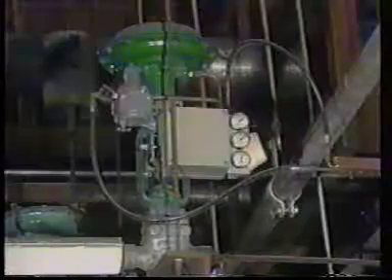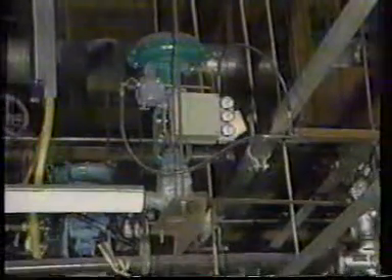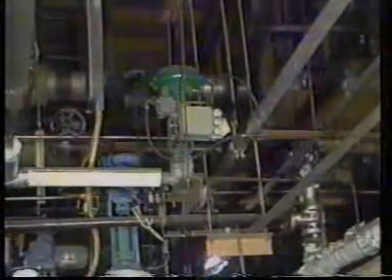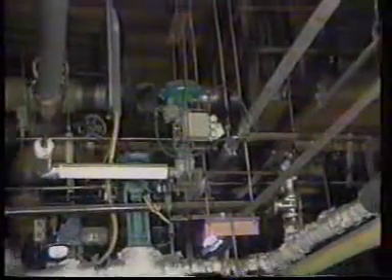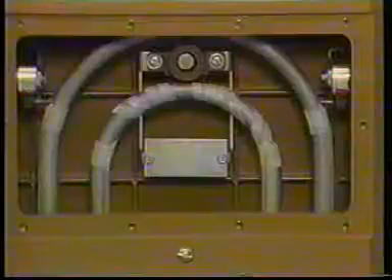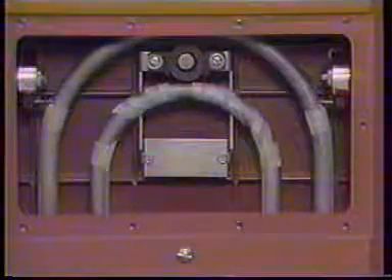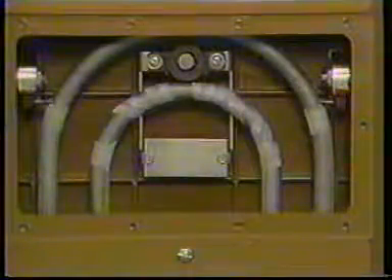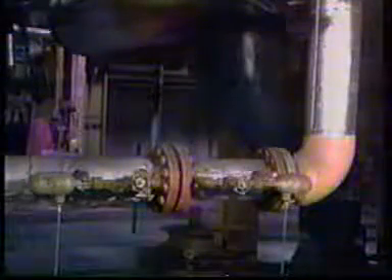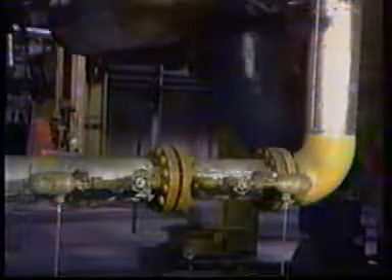As we discussed earlier, temperature and pressure can affect volume, especially the volume of gases. So when flow is measured in mass flow rate, the temperature and pressure of the fluid must be considered and compensated for. When we discuss mass flow rate measuring instruments later in the program, we'll see how these factors are compensated for, sometimes by the instruments themselves. In the next part of the program, we'll apply many of the principles we've covered so far as we look at one class of flow meters.